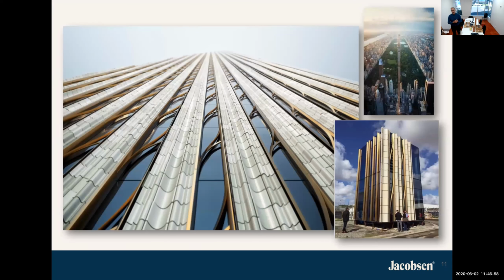This project is the big tower on Central Park in New York, a big residential unit. You'll see there how you've got the terracotta tiles running full height, but again, they're made in pods off-site and then just craned into place. So that's another couple of methods of how we can install the terracotta system without having to use the scaffolding and everything. It can be done off-site and then craned in. Makes it so much quicker.